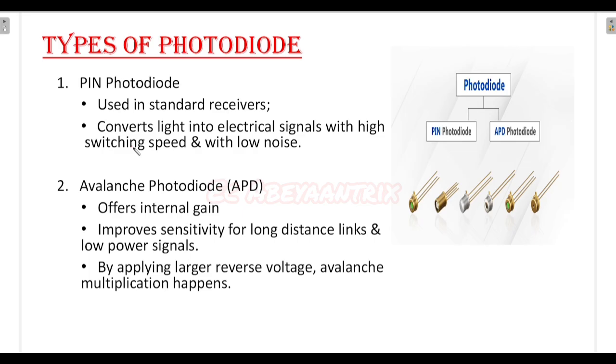So while hearing this RF switching word, you have to remember this PIN diode. The same application applies for a PIN photodiode also, because it is used with high switching speed and with low noise. So this is the main use, the key use being low noise.